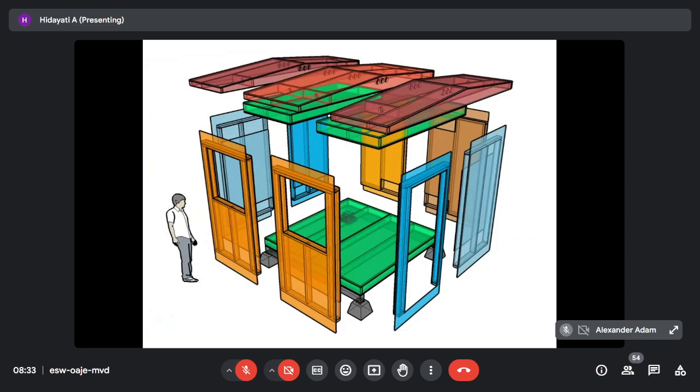So you see here all the structural elements. They are already made in the factory. These are examples of the structural elements that can be made at the factory. We can categorize them under the IBS system. So you can see here, this is the wall panel, the orange color, that is one example of a wall panel.